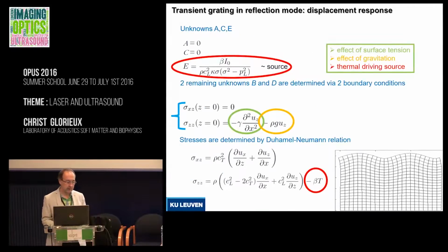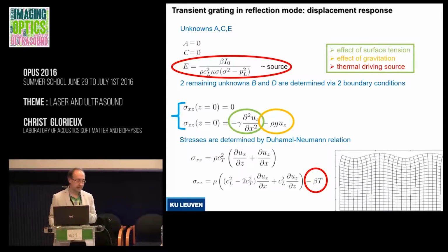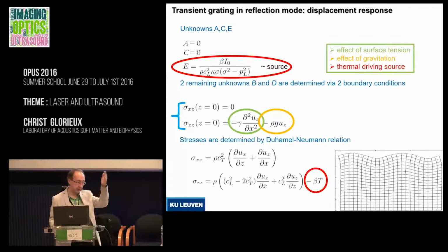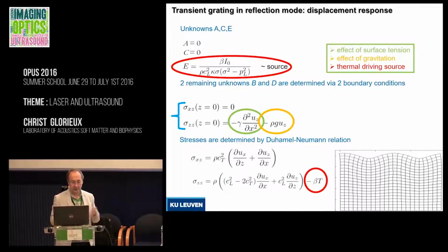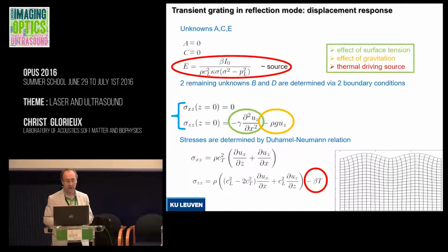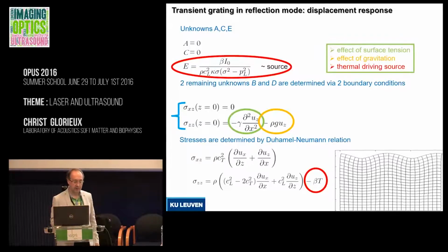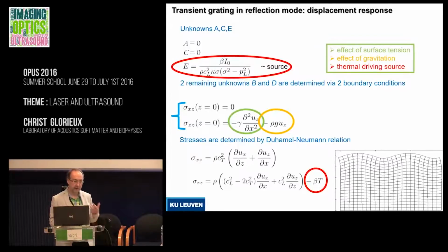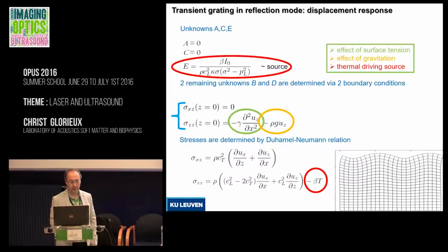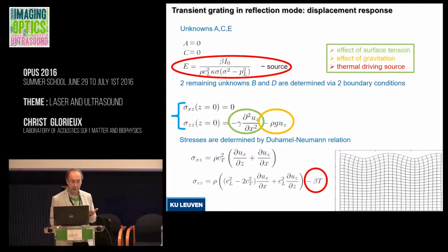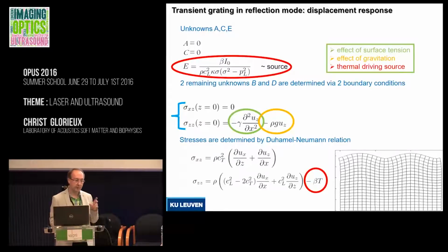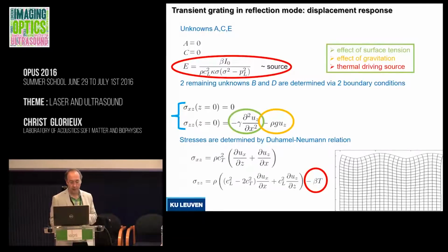The special thing about these surface waves is that there's this boundary between the surface and vacuum or air. And at the boundary it's free of stress. It can move freely. And this is a condition that we can use to find particular solutions of the wave equation. So the important things are stress. Hooke's law is important, which couples stress to displacement, and of course the source.